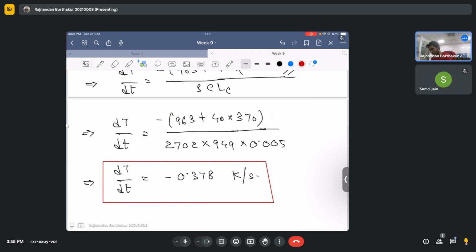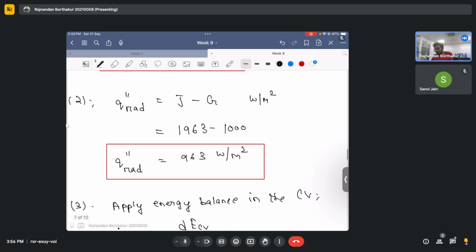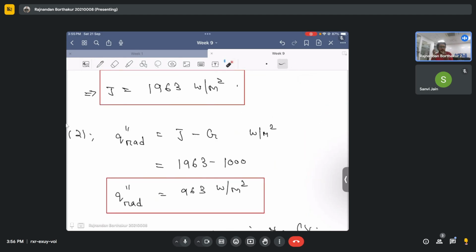All right, so I think it is clear how we calculated the rate of change of temperature of the body. Let me repeat why we did this. For this body, we have two modes of heat transfer taking place: the net radiation flux that we already calculated, and the convective flux, owing to the fact that the body is exposed to a fluid having a heat transfer coefficient h infinity and a temperature T infinity.